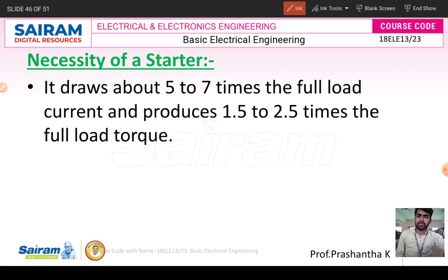Once the rotor starts rotating, what happens? It creates EMF, and once the rotor starts rotating, it will run smoothly. So the starting current is 5 to 7 times, and also the torque required at the time of starting is 1.5 to 2.5 times the full load torque.